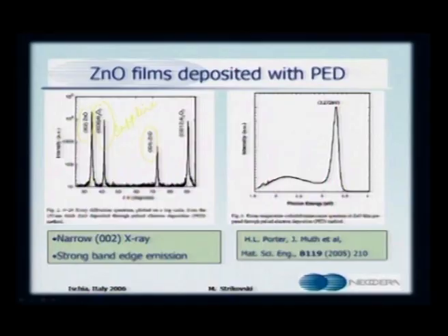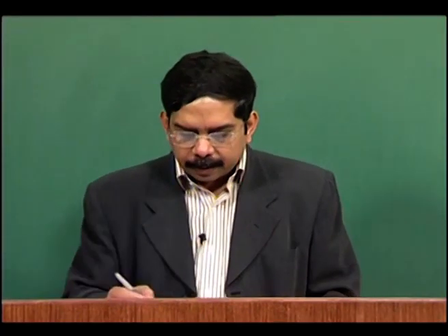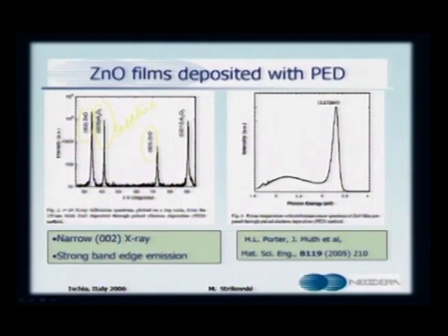So, zinc oxide is actually growing on the C plane of your sapphire substrate, therefore, you would see only reflections of that, and the way you see the intensity of your C axis grown zinc oxide, it clearly shows that they are very highly oriented thin films, and you can make epitaxial films out of it.